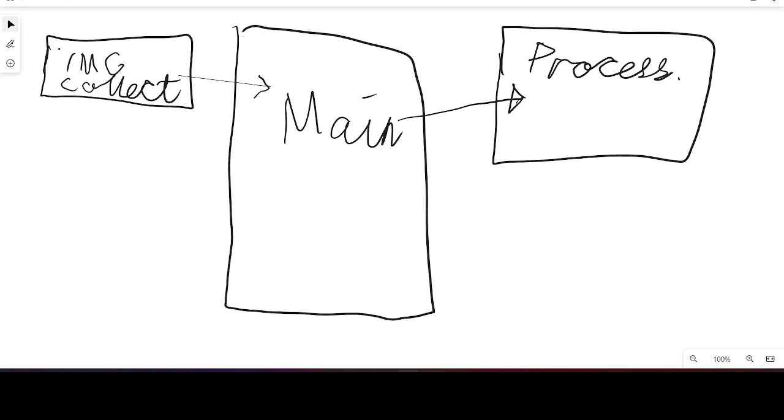When it has found a sufficient amount of neighbors with the corresponding color, it says I found the blue patch, for example. Then it finds the mean position of all the blue pixels, and that will be the position for the blue patch. So then it returns 5 locations for the patches: 1 blue, 1 red, 1 green, 2 yellow. That's sent back to the main loop.